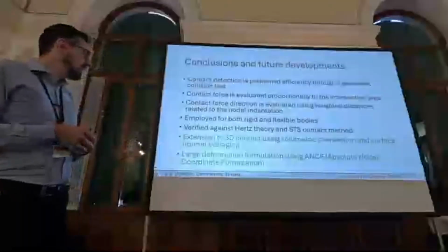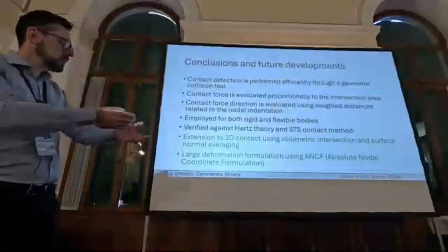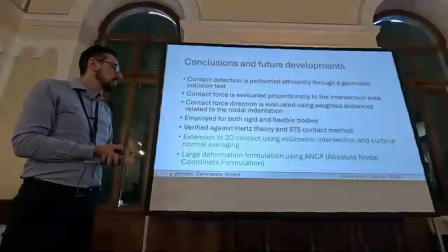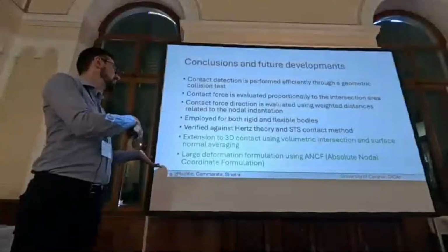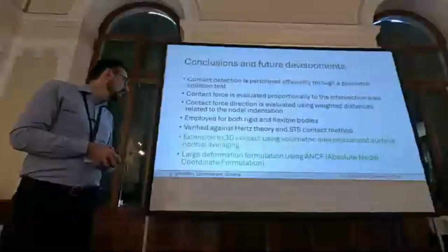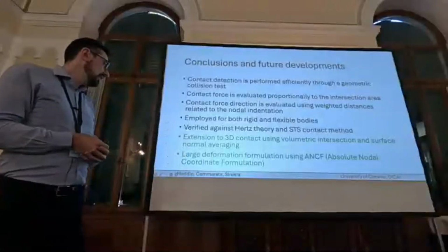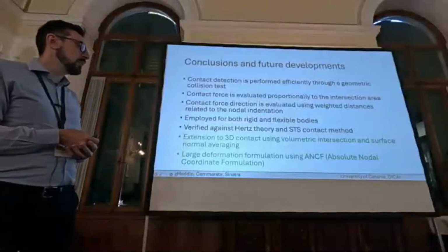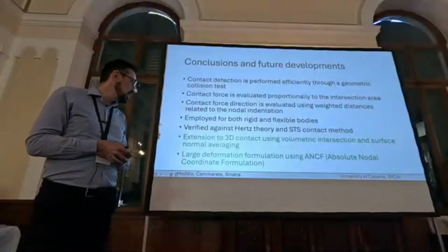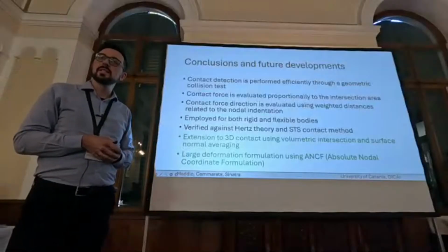Future developments, we will extend to 3D contact using volumetric intersection and surface normal averaging, and the next step is large deformation formulation using the absolute nodal coordinate formulation. Thanks for your attention.